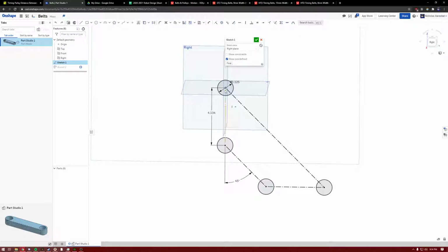So if I increase this, and this is how I always do these adders, I would always keep the dead center there, because if you don't, you might forget that you changed it later. So let's say it's plus 0.04, right? That's right. Okay, cool. Plus 0.04. What that would do is increase the tension between these two shafts.